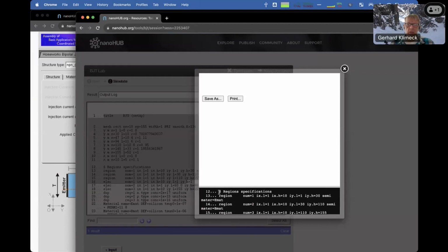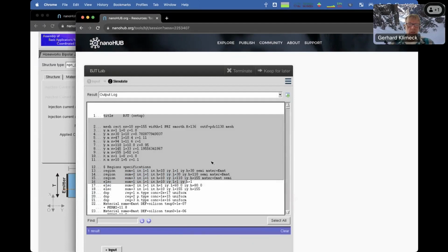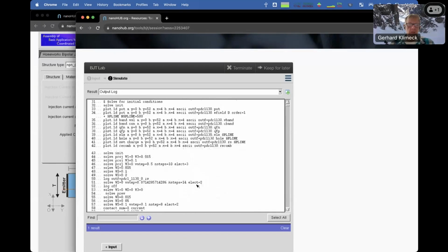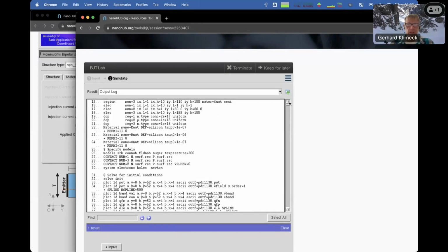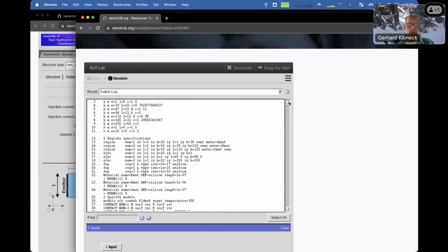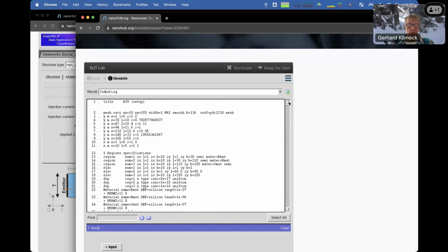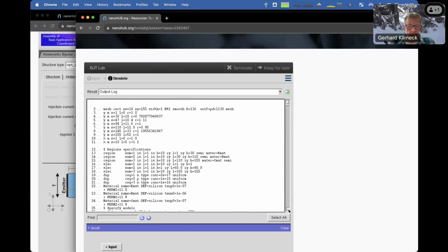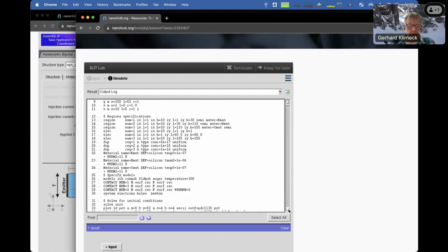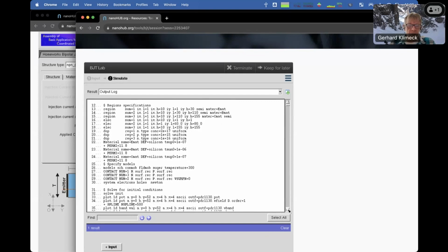You can basically copy and paste this code over into the Padre input deck, and you can set the temperature. If it's not set, then it's defaulted to 300. But in the region, you can set temperature. Let me see if I see it. In principle, this could be a feature request to want to model cold temperature BJTs. And I know, oh, here it is, right?